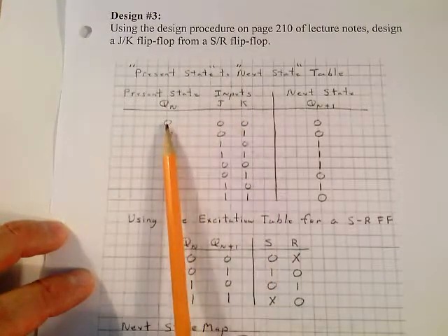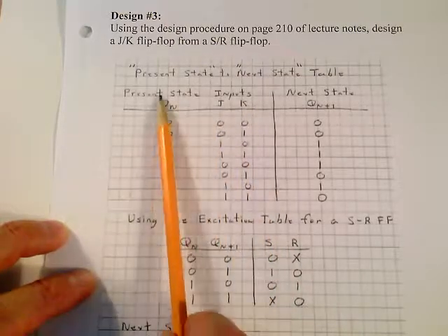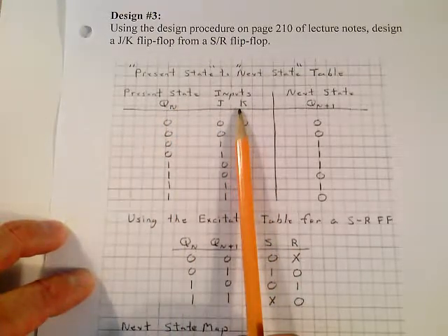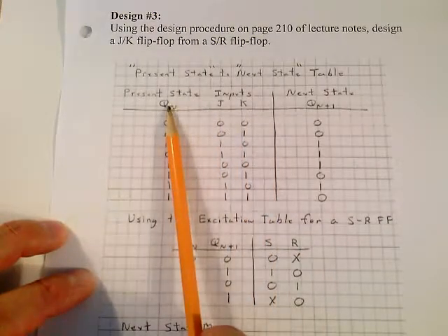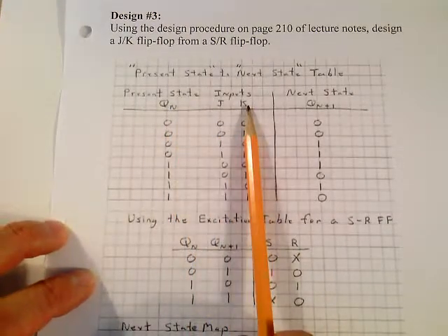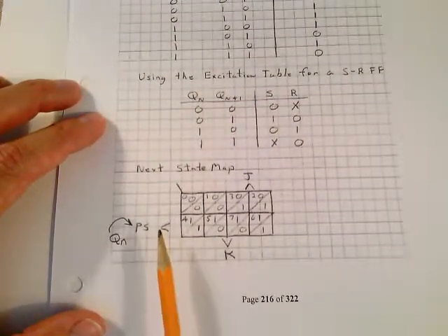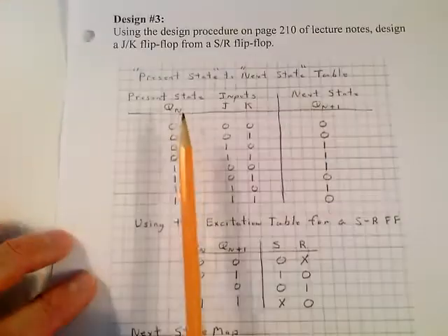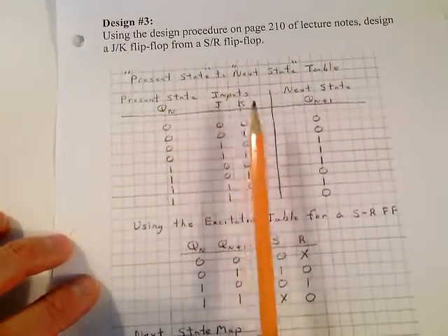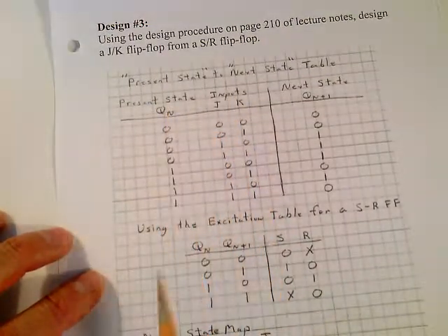And notice we just list them sequentially. Now, you could put these in any order. You could put the inputs over here and the present state on the right-hand side. It doesn't make any difference how you do it, but when you lay it out as the most significant bit to the least significant bit, look down here, when you do your K-maps, remember, this was usually your A, your B, and your C, and we had this listed A, B, and C for K-maps, so you have to be careful. However you put this up here, your Q sub n goes down here.